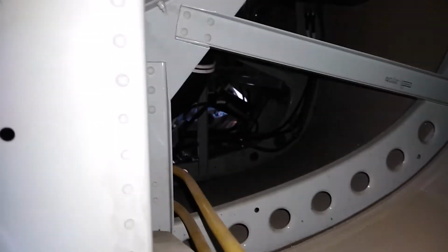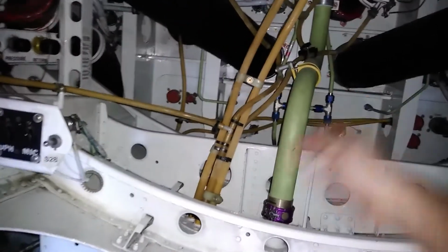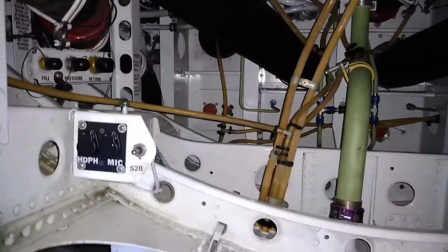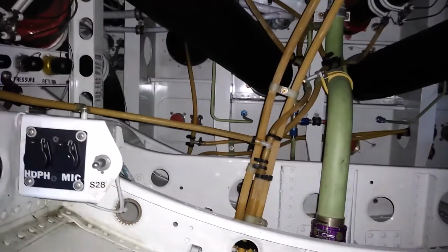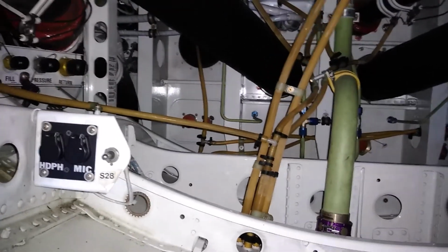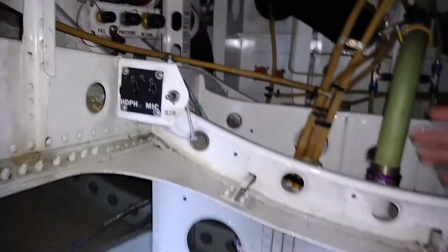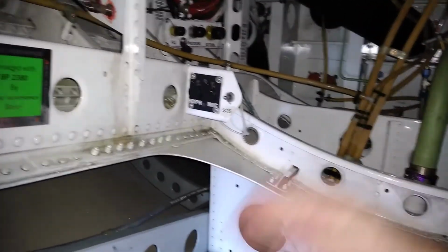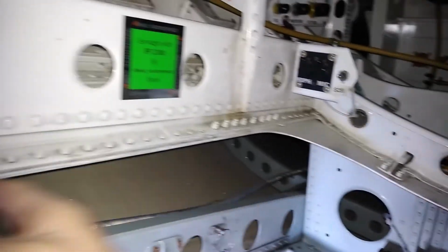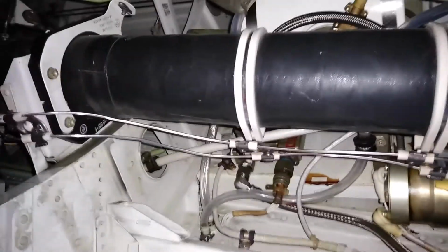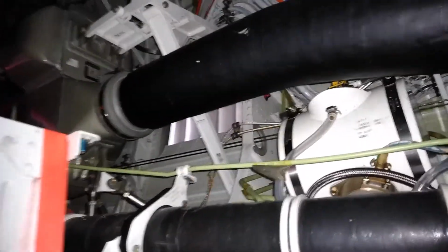And the reason they vent that through under the wing and all that is to keep a constant flow of air carrying away any vapors from greases and hydraulic fluids or fuel. In the event that there's any spills, it gets vented with a constant flow of air flowing underneath all that, blowing it back here. And from the aft equipment bay, this whole area gets vented.